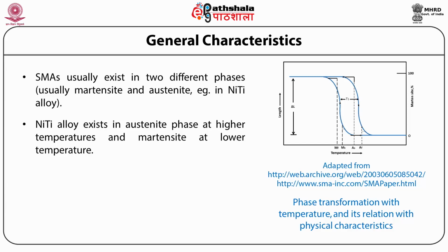Similarly, when we take a material which is at a temperature below MF and start to heat it, then during heating, the parent phase will start to appear at AS, and the transformation would be complete when the temperature reaches AF.